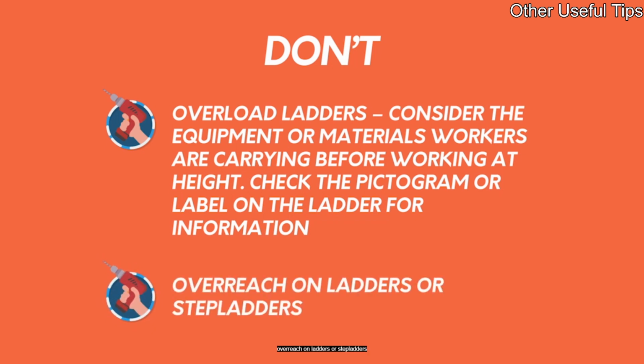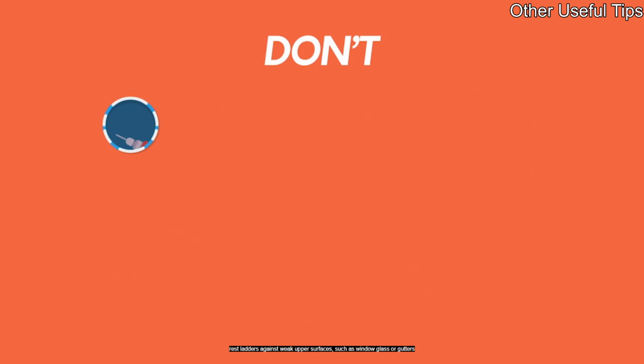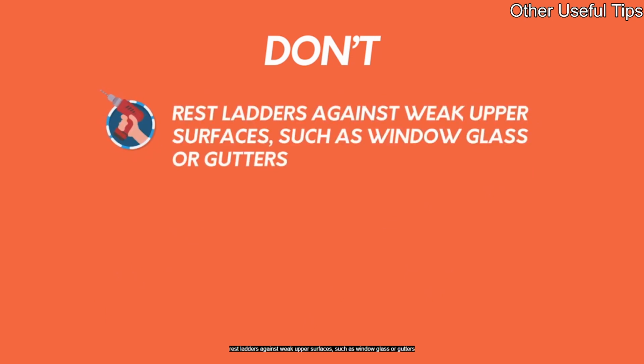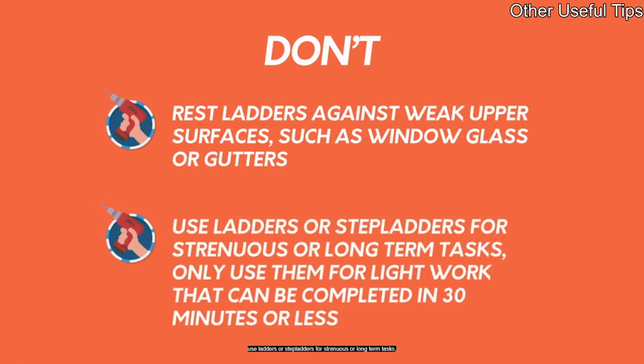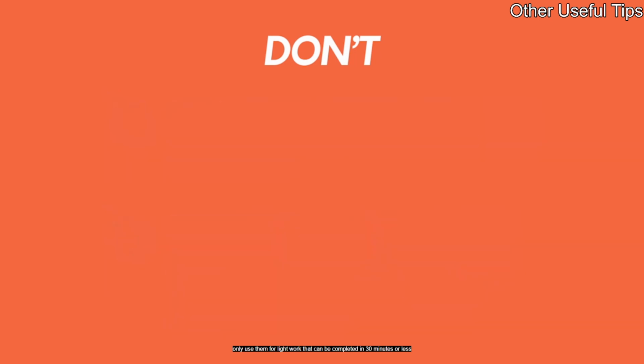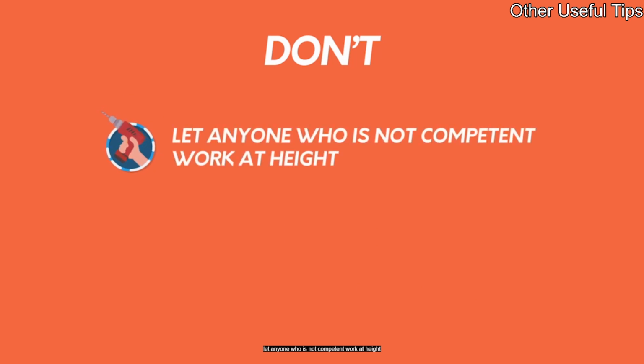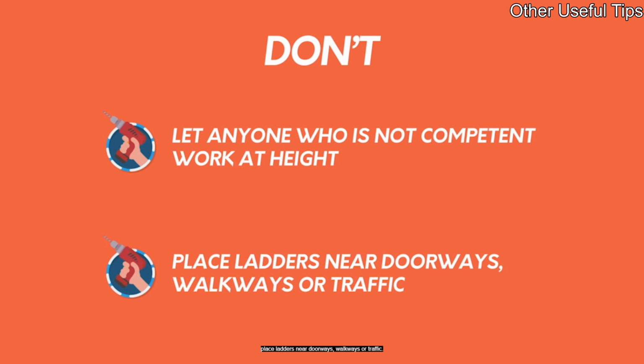Don't overreach on ladders or step ladders. Don't rest ladders against weak upper surfaces, such as window glass or gutters. Don't use ladders or step ladders for strenuous or long-term tasks. Only use them for light work that can be completed in 30 minutes or less. Don't let anyone who is not competent work at height. Don't place ladders near doorways, walkways, or traffic.